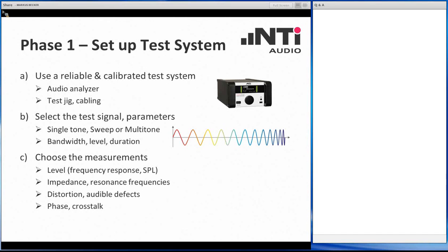And last but not least, you have to make sure that you are applying relevant measurements, meaning measurements that are able to unveil the actually occurring defects in your device. If you execute a measurement that measures something which never goes wrong, that doesn't make sense. It's just adding complexity to the whole setup. So please, this is something you have to really do for your device individually. Find out what are the relevant measurements, those that allow you to reliably unveil possible defects.